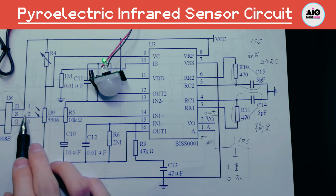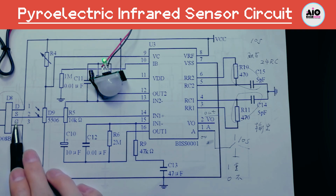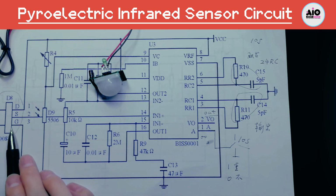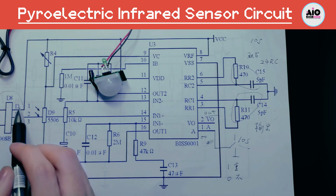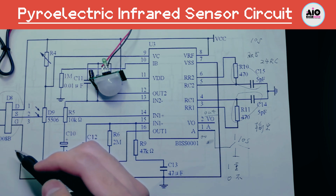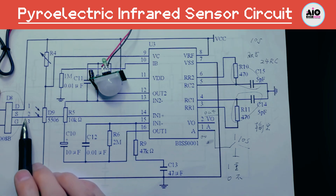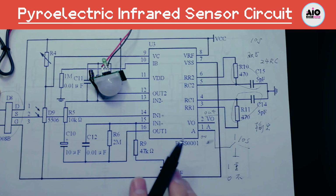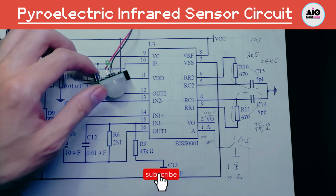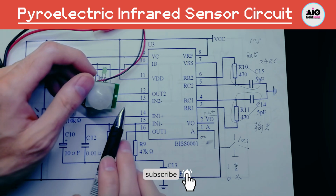In fact, its final stage is equivalent to a field effect transistor. Its signal output is relatively weak. After integrating this amplification part internally, the output of this pin can directly control a load of small current. If a large current load is needed, the relay can be driven directly through this pin, so its external structure will be relatively simple and its size will become smaller.